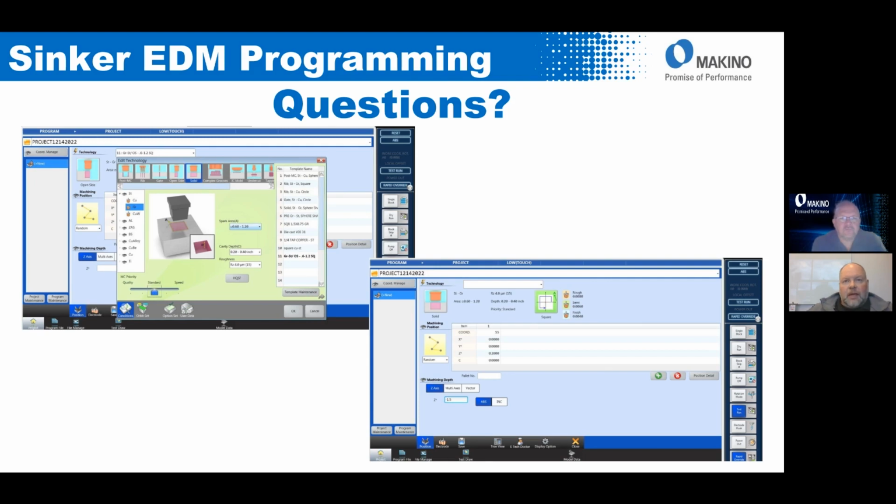So anytime we add off time, it's going to add wear to the electrode and then also add cycle time. So we're trying not to do that. That's where the adaptive spark function comes in, or AISF, to change the jump first. And then if it still has issues, then we go after the off time to adjust that on the fly.